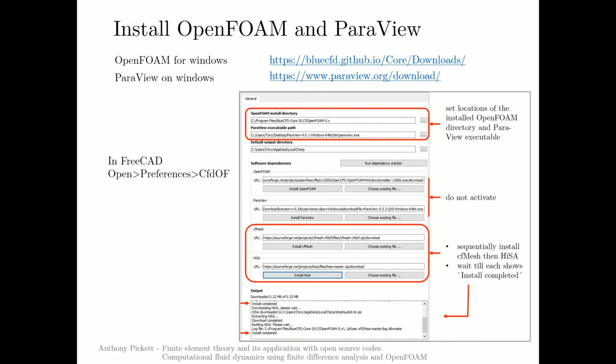The next thing you have to do is to install OpenFOAM. Now there are different possibilities. I'm only talking about Windows here. On Linux this may be more straightforward, but on Windows there are two possibilities. You can download an ESI version, which uses a virtual box and various other linking software to run a Linux version of OpenFOAM on Windows and make communications.